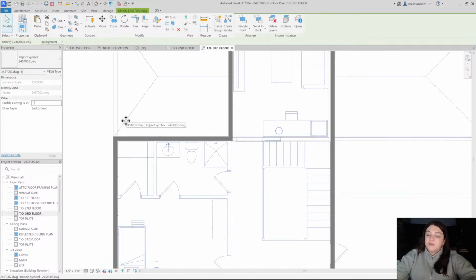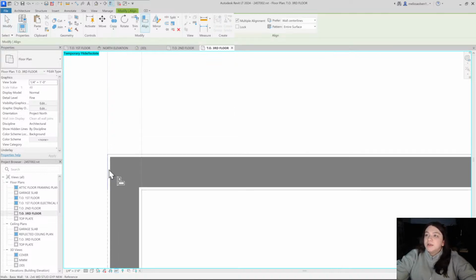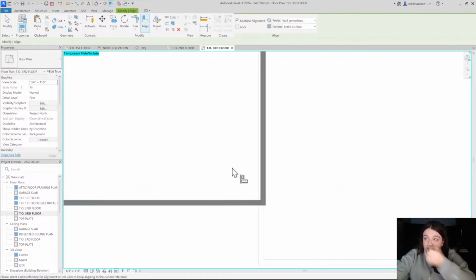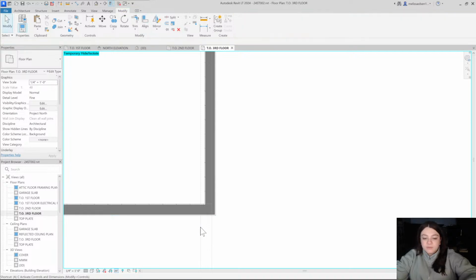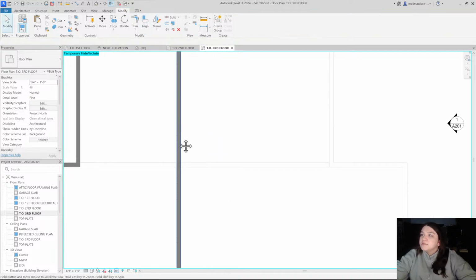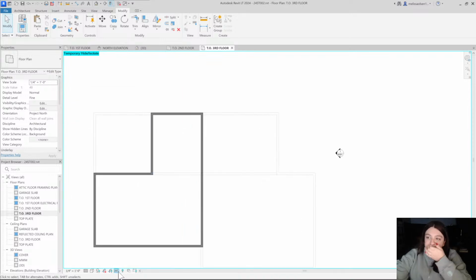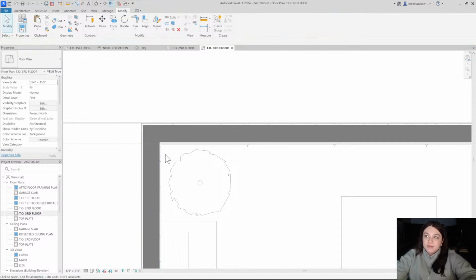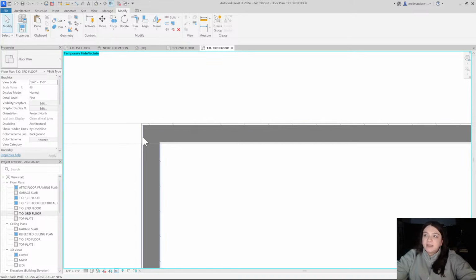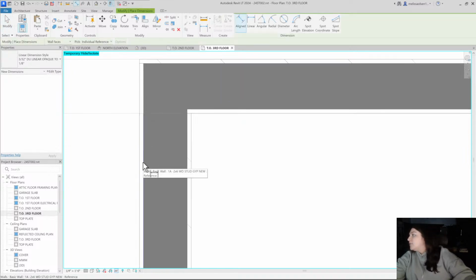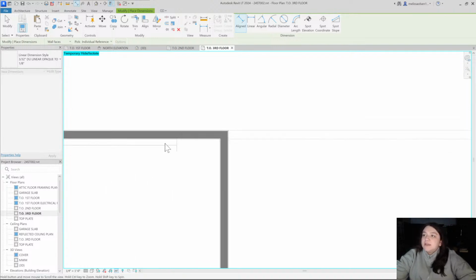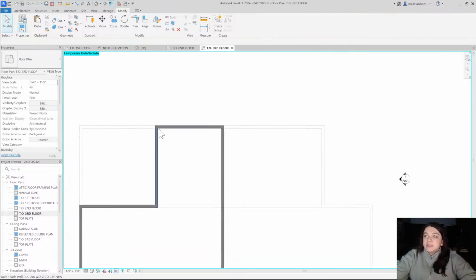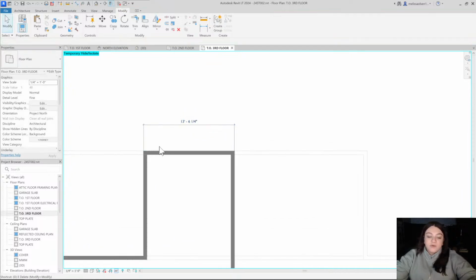and I'm going to turn off this roof, and I'm going to go back in and make sure that these walls are in fact stacked on top of each other correctly. This one looks like it could use some adjusting, and everything else is basically me drawing it. I keep temporarily hiding the CAD plan below, which is HH, and then I keep turning it back on. So if you see it coming on and off, that's why, because I'm using it as a reference, and I don't want to accidentally click or select a CAD line. I really want to make sure that I'm selecting the Revit walls.